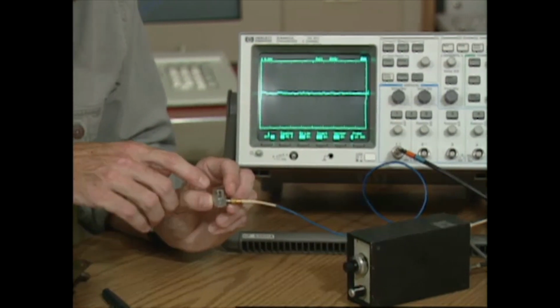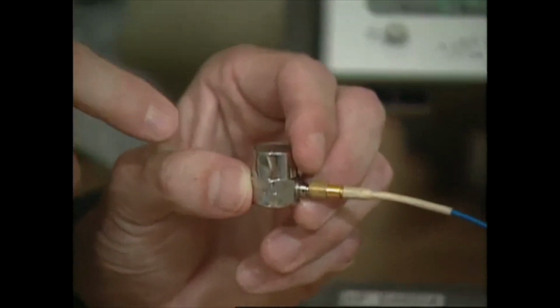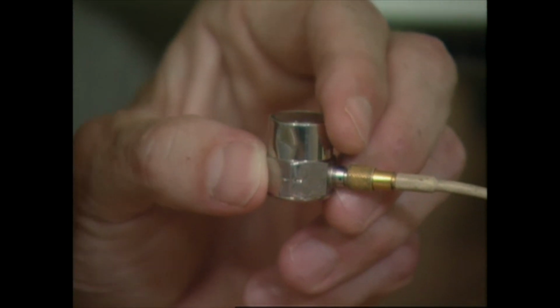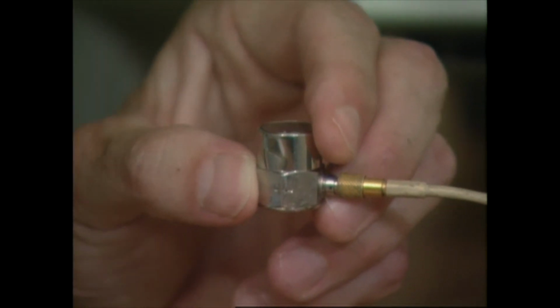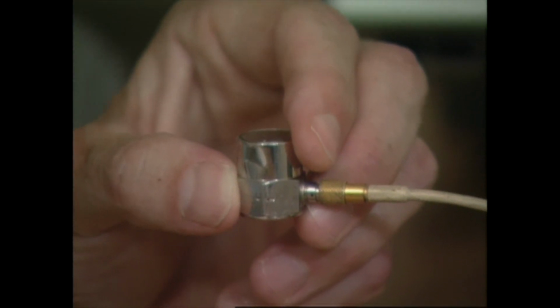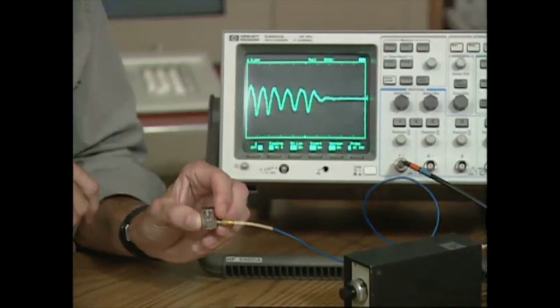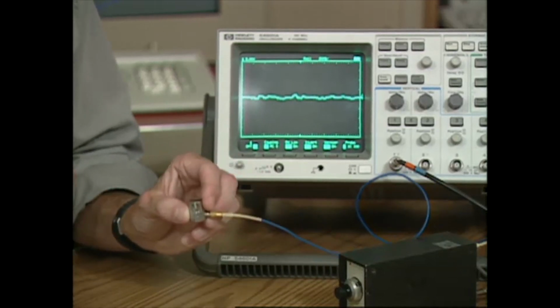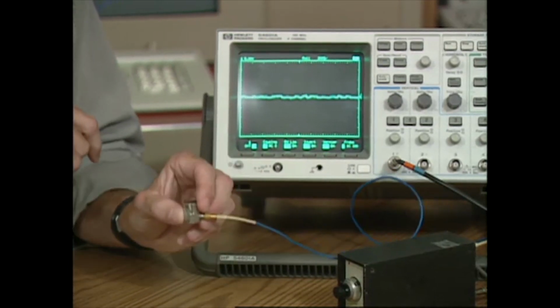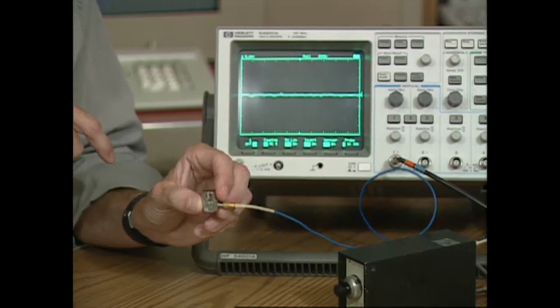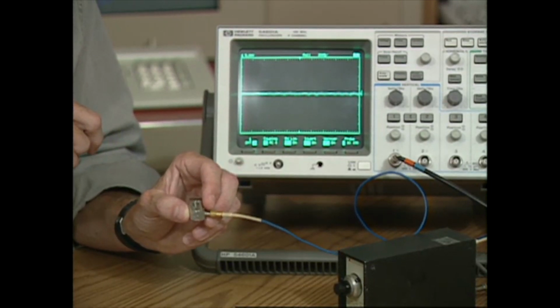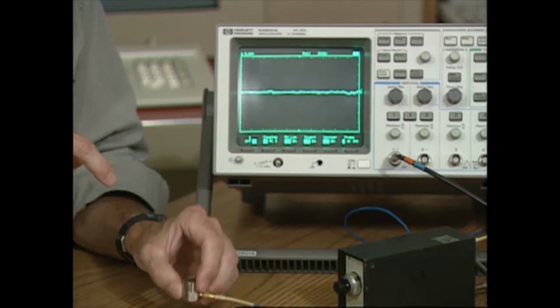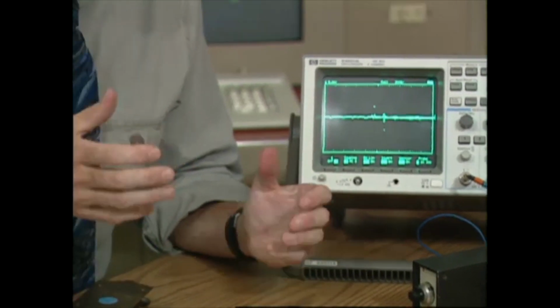Another thing to notice is that this particular accelerometer is really only sensitive in one direction, and that's very common. Right now, its direction of sensitivity is up and down. Okay, so again, if I move it up and down, I get a pretty good signal. If I move it left and right, you can see that I don't get too much of a signal. In fact, any signal you do get is just due to the fact that I can't move it left and right perfectly.